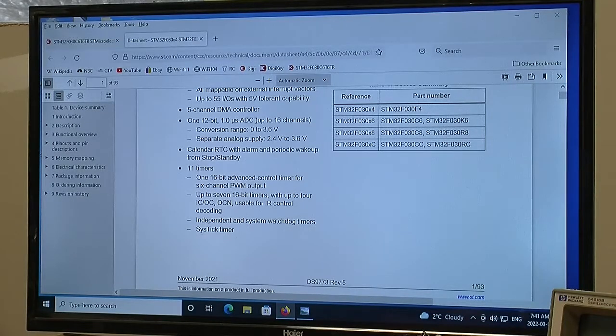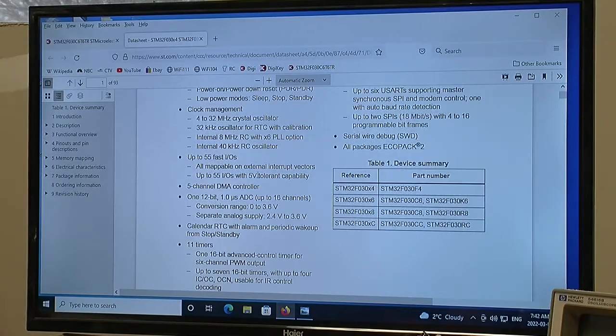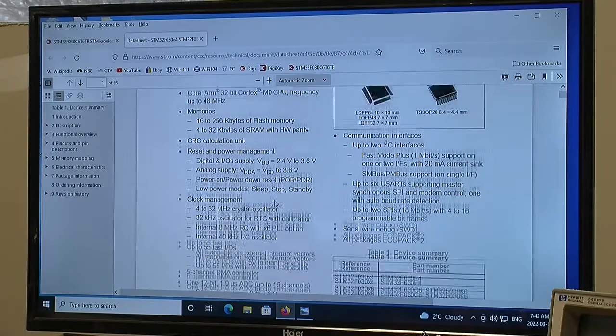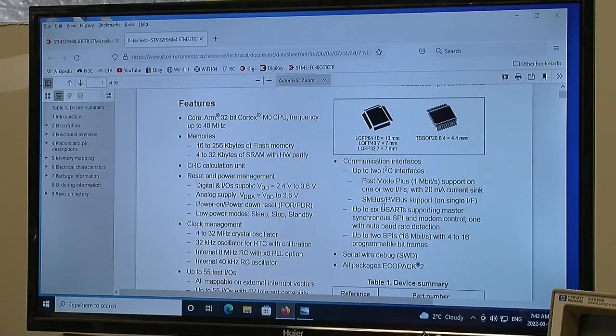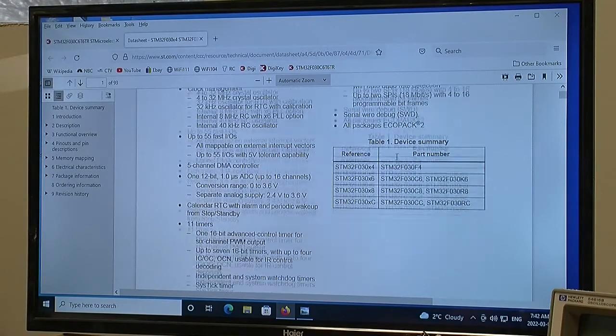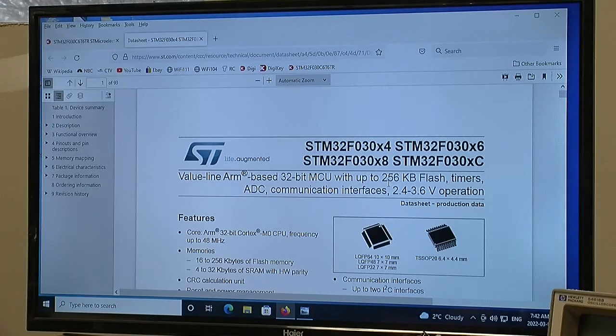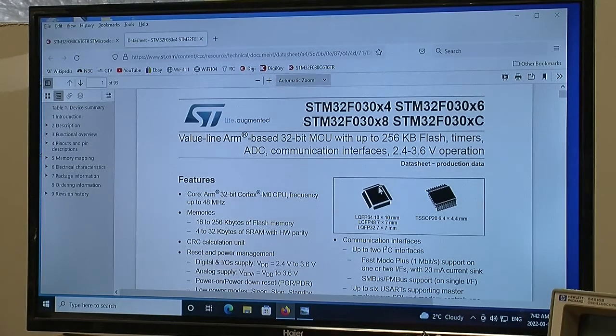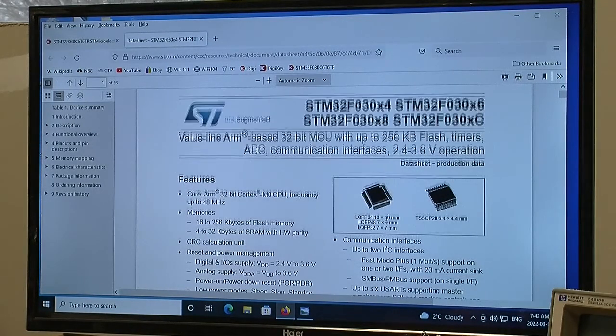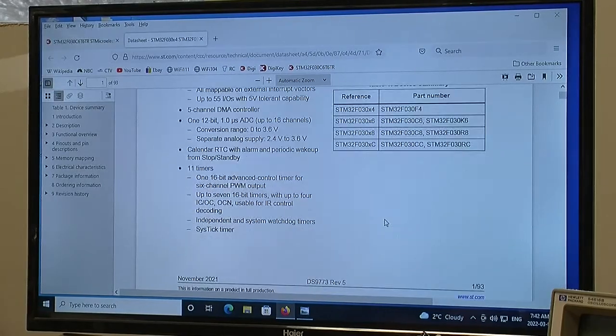And there's also an analog to digital converter over here that could be used to measure the temperature. There might also be some sort of, say, I2C or SPI temperature controller or sensor somewhere on the board. So there you have it for $1.30, quite a respectable little microcontroller that probably does more than anything one would ever need to do in an application like this.